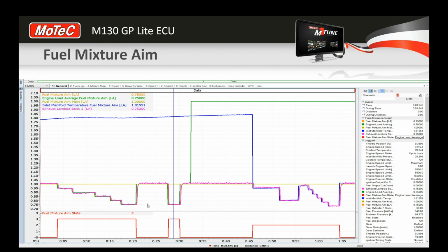So if you do the setup properly, and your injector calibrations and things like that, you can expect something pretty good like this. So once you've tuned the engine, if you want to make the engine richer or leaner for any reason, maybe you want to start richer for safety, and as time goes on you want to lean the engine up, you don't change the engine efficiency numbers to make the engine leaner, you change the aim.